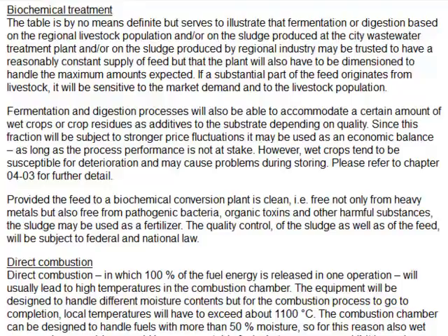If you have access to a flow of a substrate suitable for biochemical treatment, then that plant will have to be a base load plant, running all the time, accommodating the whole flow and working all year round, basically. The substrate cannot easily be stored.